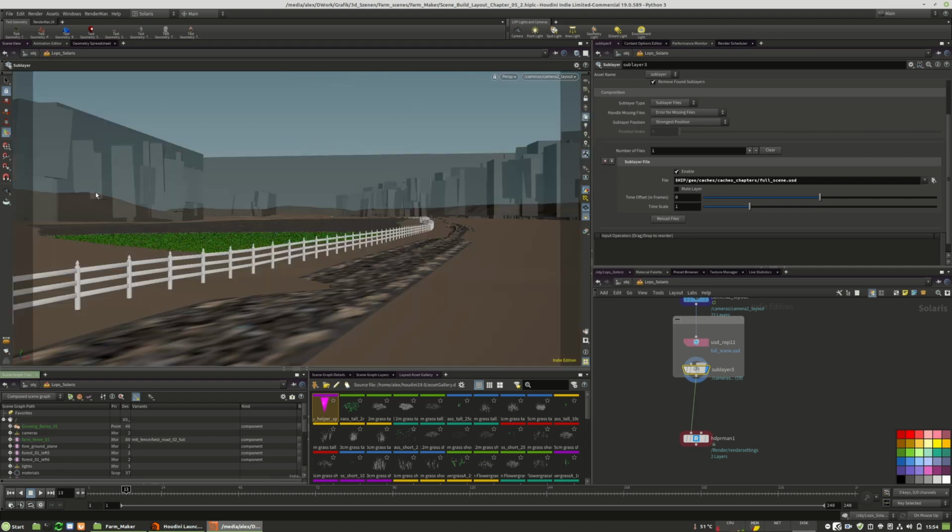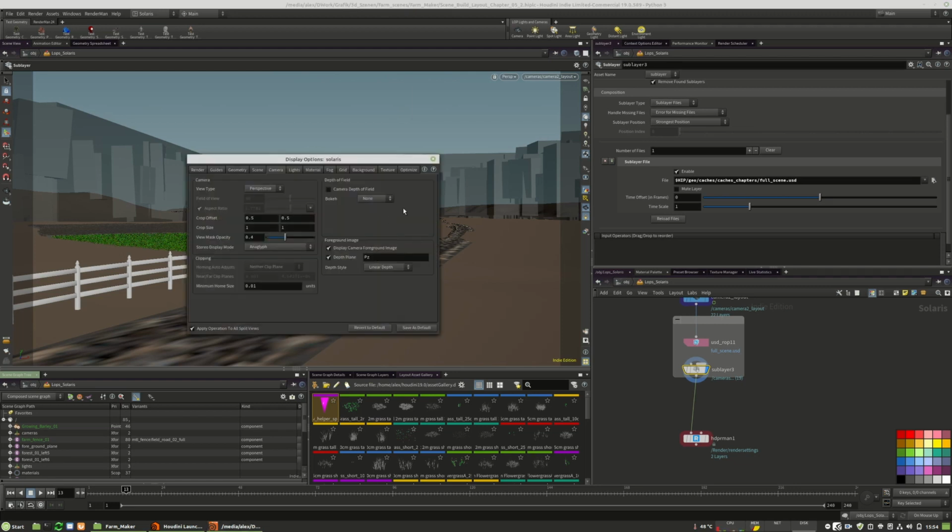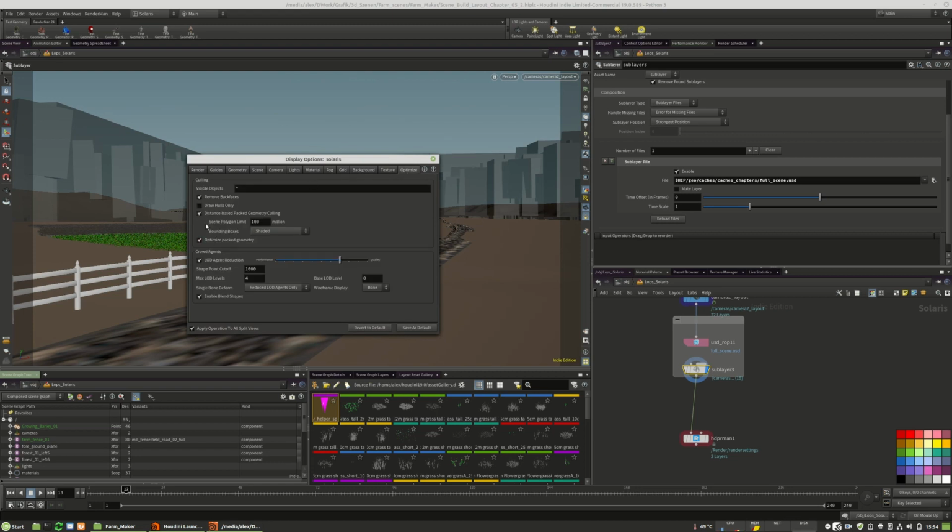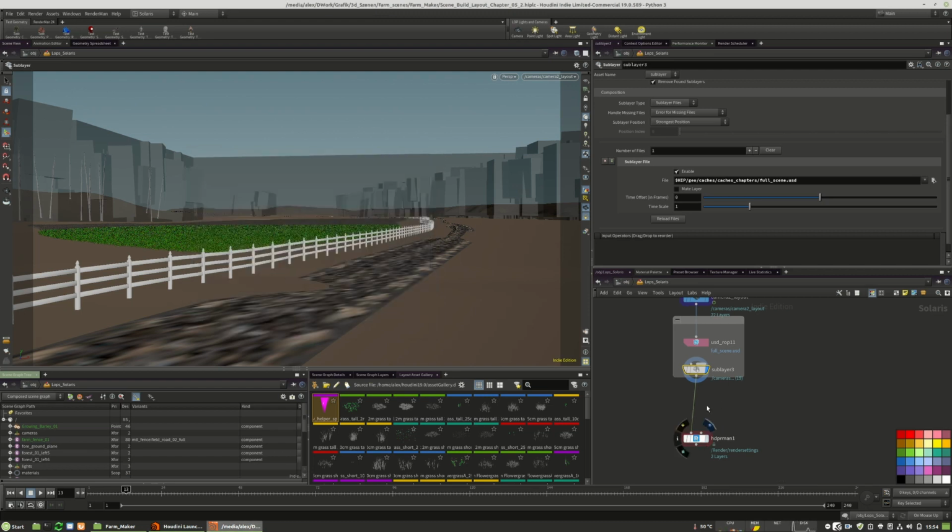And as you can see, Houdini tries to get some space in the viewport. What we can do is hit D and go to optimize and increase the millions of polygons that are currently visible. So maybe to 500 million. And not even this is enough. But yeah, we will try to make it work. I will save this file once again.